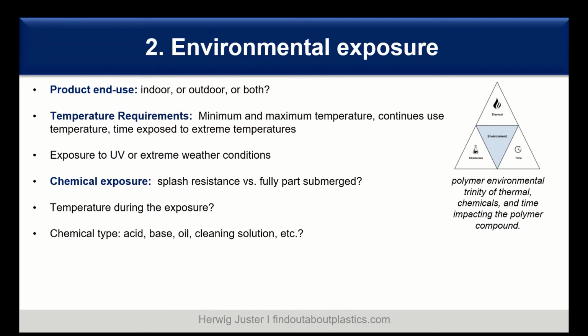Is the part exposed to splash only, so you need splash resistance, or is the part fully immersed in a chemical like oil? And important is also the temperature during this chemical exposure. This can also heavily impact the polymer material. Also important is the chemical type, to find out if it is acid, base, oil, a cleaning solution or something else.